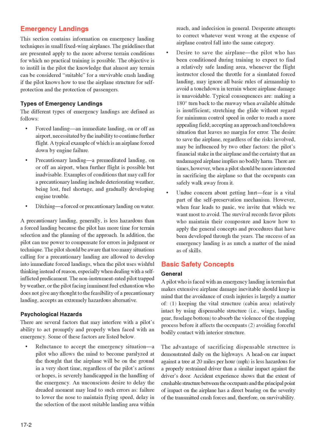Desire to save the airplane. The pilot who has been conditioned during training to expect to find a relatively safe landing area, whenever the flight instructor closed the throttle for a simulated forced landing, may ignore all basic rules of airmanship to avoid a touchdown in terrain where airplane damage is unavoidable.